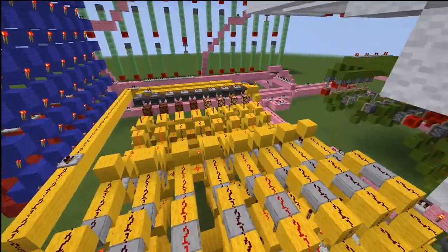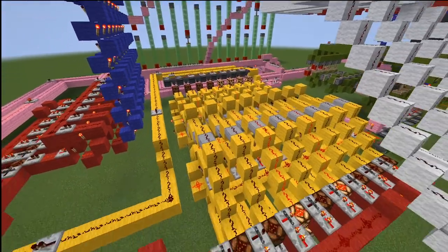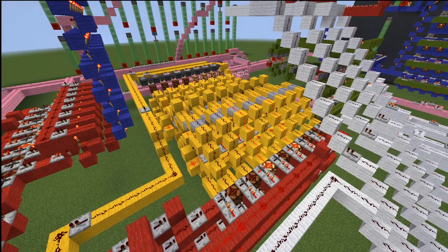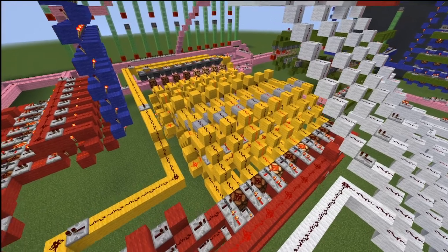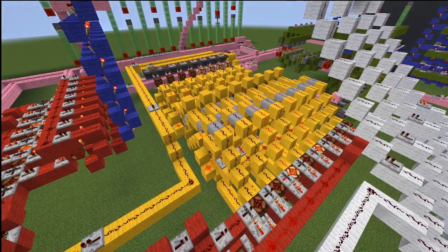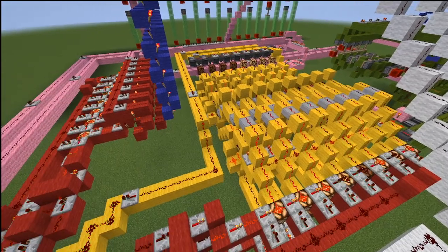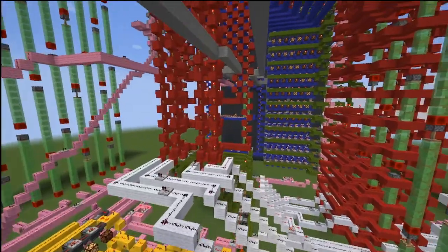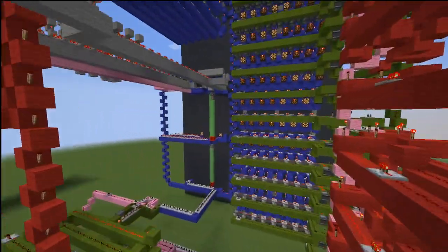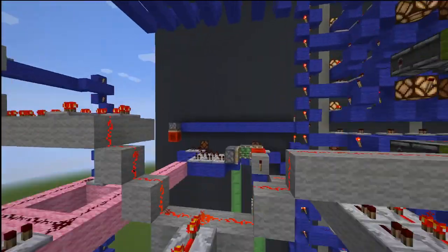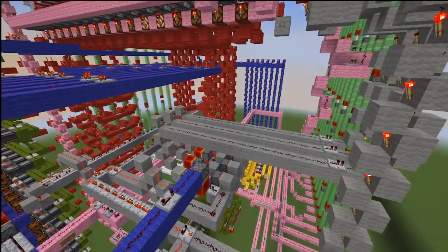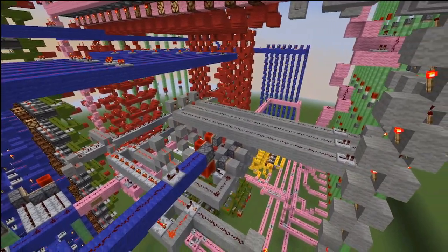And now that's going to perform subtraction, and any minute now it's going to store that into the A register, which will wrap up the subtraction part of this program. Should be updating that right about now. There it goes. So it stored it into the A register, as we see here, and that's it for the subtraction macro instruction. So now if we come back up to our clock and our control unit here, we have to wait another 2 clock cycles.